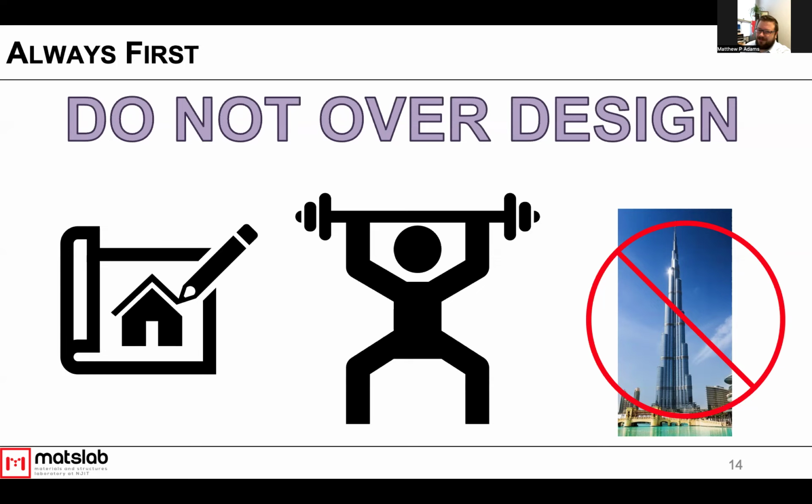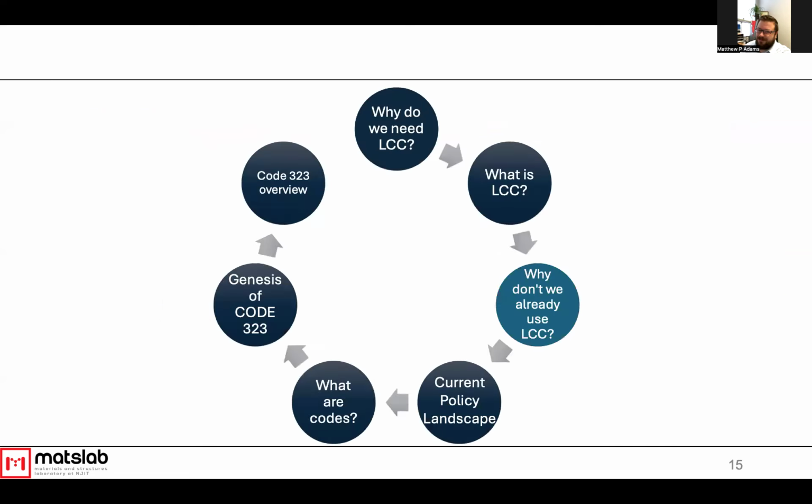That concrete is over designed. You're getting too much strength too early. That means you have too much cement. We need to start thinking about ways that we can set upper quality limits to prevent too much cement from being put into a particular mixture.